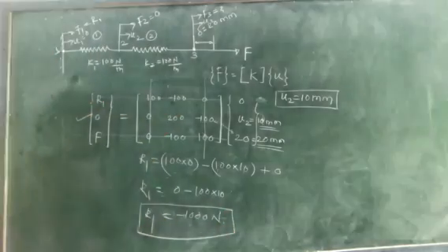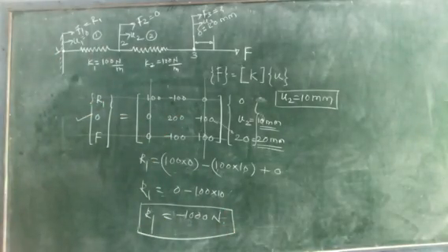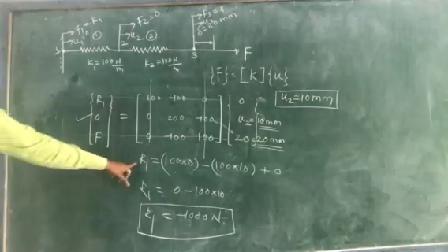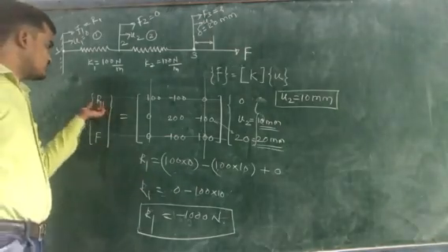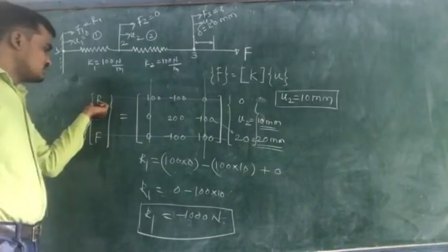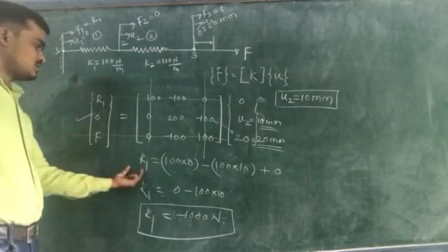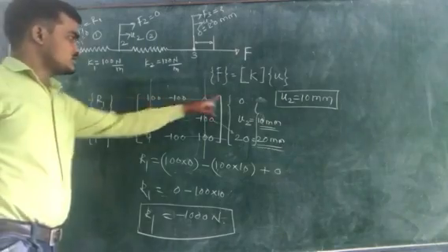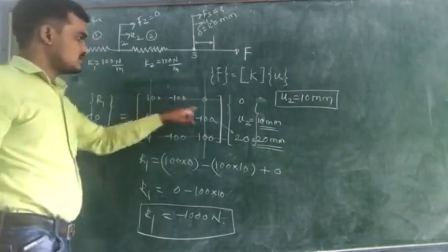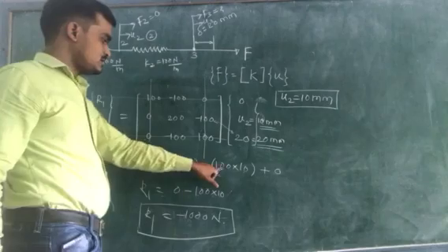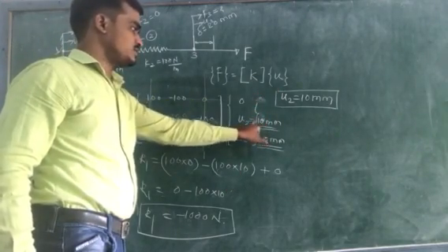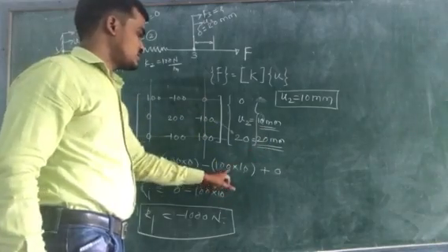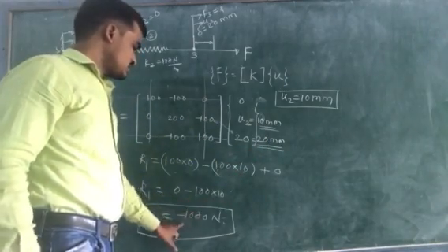So this is your R1. Okay, so how have we found this R1? Take equation 1 first to find out this R1. So R1 will become 100 into 0, minus 100 into U2. As we know, the value of U2 is known now because we have found this value. U2 is equal to 10, so minus 100 into 10 becomes minus 1000 Newton.